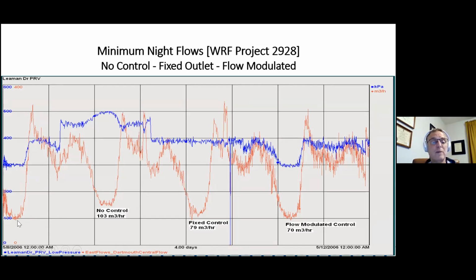And yes, folks, there is some active leakage there, and we actually did find some leakage in this system afterwards. But nonetheless, there's your night flow, and there's your morning peak. People go to work, and then they come home, and then they take another peak again around supper time. So this one clearly shows a nice pattern that you'd expect in this DMA. It's a combination of residential and commercial. So this one behaves a little different than the one that I showed you earlier.